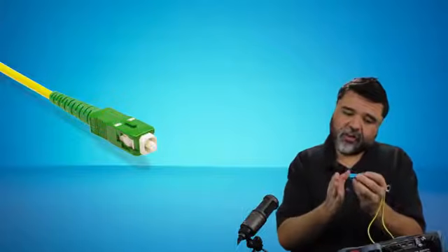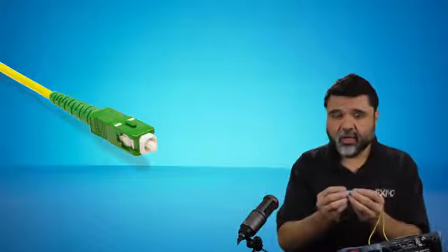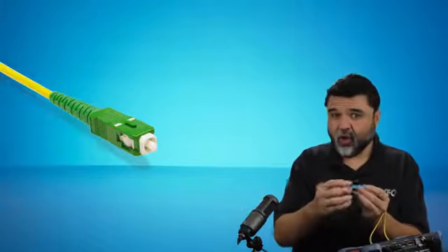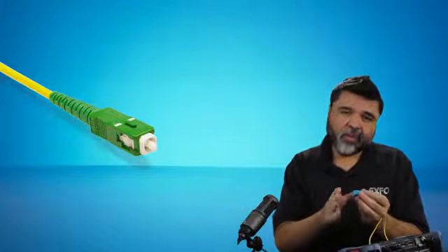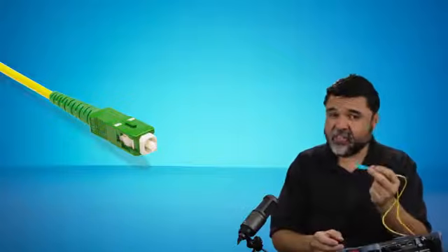So when you amplify a signal, reflection of a connector is a percentage of light that's being returned. And so as you inject more power, of course, your total power coming back, percentage-wise, is going to be the same, but the total power value coming back is higher, of course, than if it had a lower output power transmitter. And so because of that, a lot of the cable TV companies have been using APC connectors for quite some time.